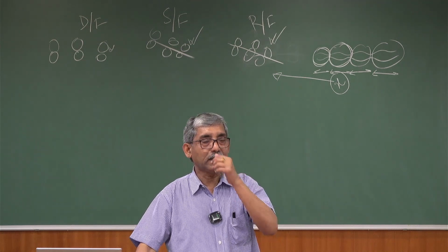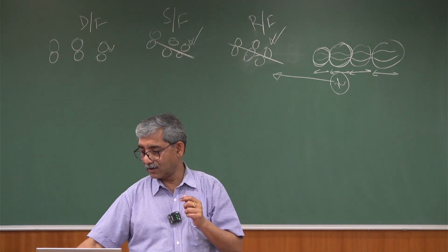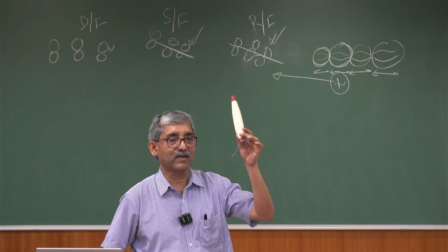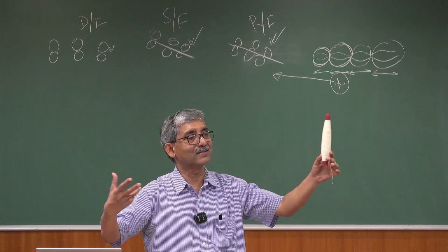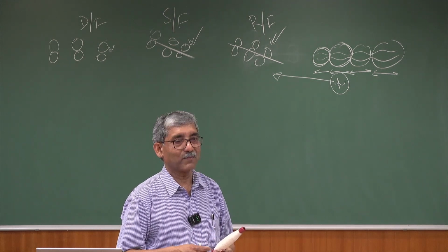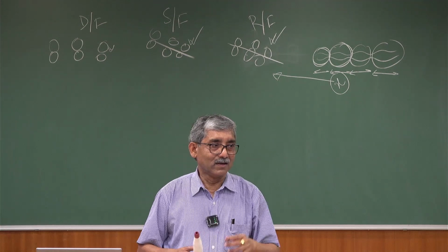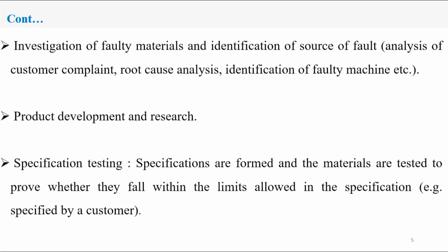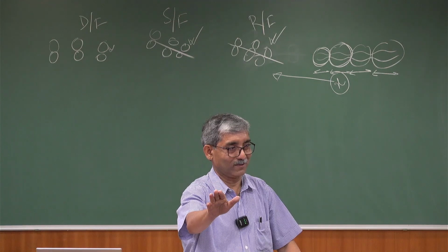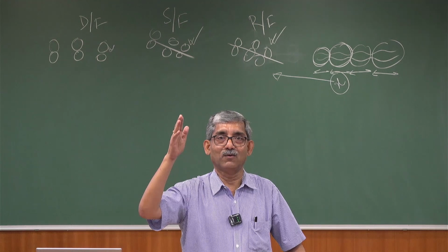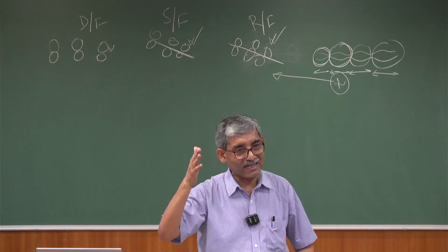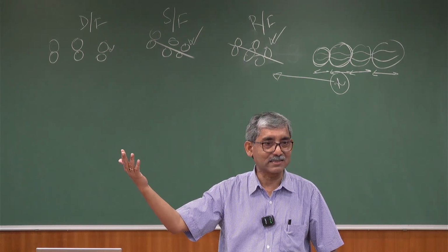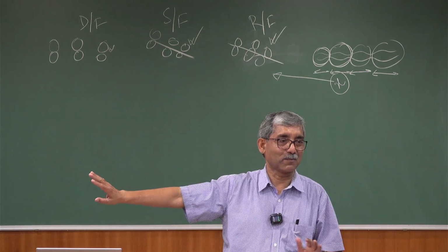Now the thing is, suppose they need a strength of 10 centinewton per tex for a particular yarn, and you are giving higher strength. The higher the strength, the better the quality. Now if they are asking for 10 strength and I am giving 20 strength and I am very satisfied, it is serving my purpose.